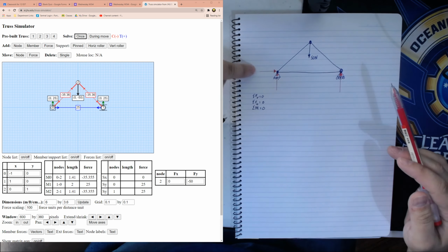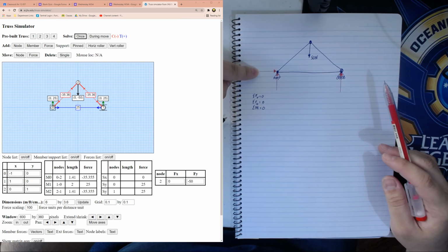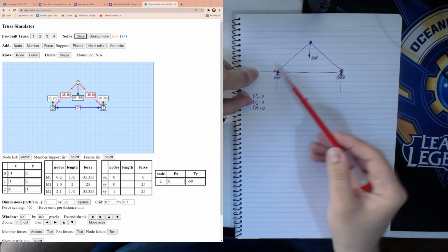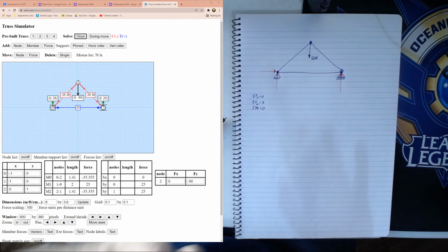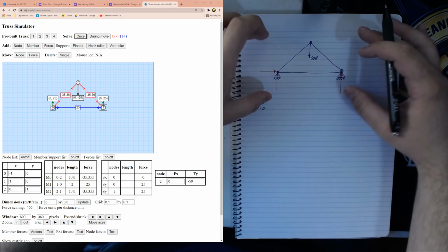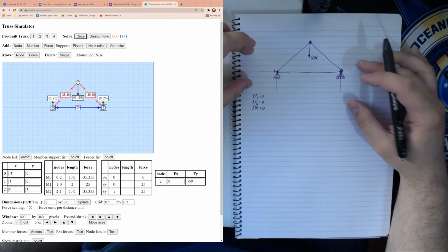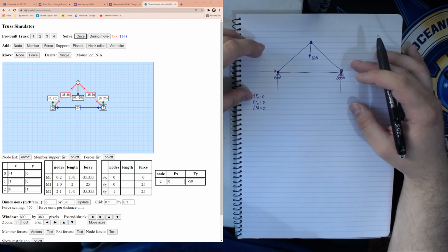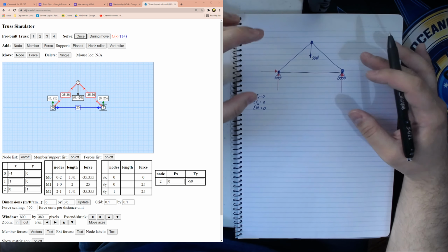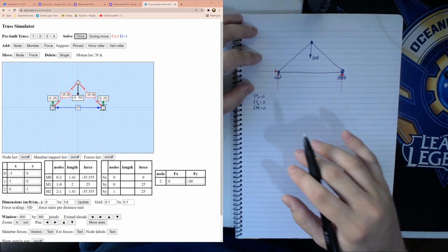We also might see that this arrow is going to the right, but when we do our sum of all forces horizontal, there's no other horizontal forces, so this one is going to equal 0. But I digress, we will get to that later. All right, so now we have drawn all the forces and all the reaction forces in this scenario. We are now able to solve it.